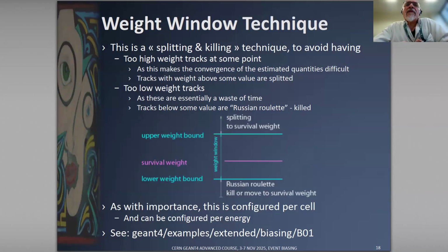So the idea is that you have learned about your simulation where the typical weights you can expect are, and you set up weight windows which are volume or geometry dependent. If a particle has too large a weight compared to this weight window, then it will split, so that each of the copies will fall inside the weight window you have defined.